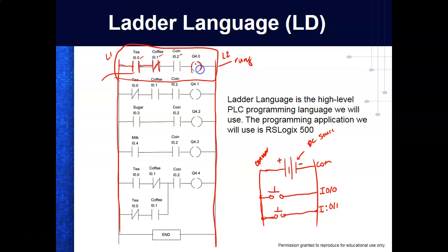For this PLC, it's actually going to be two parentheses like this. This represents an output port. So this is output. On ours, on Allen Bradley, I'd have a wire, and I'll come over here and hook it up like this. And we'll talk about the difference. And then I would run this to all my output devices.